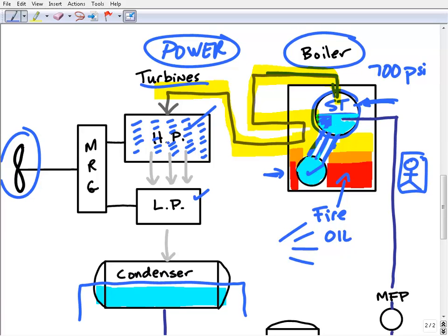So here are these fan blades. You've got this superheated high pressure steam that's going to come through, and it's going to go into this chamber. Think of it almost like a jet engine, if you will, and it's going to spin it around, or turn the fan blades mechanism, and it's going to spin. Now what it's doing is spinning the shaft, and I'll talk about this in a second, and that's connected to this MRG. That's a transmission, if you will, but we'll hold that thought for a second.